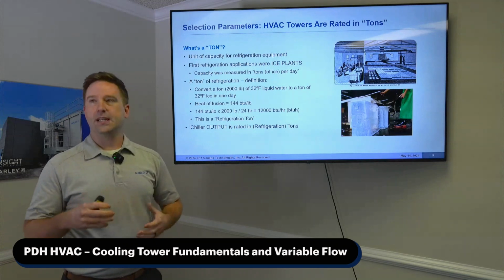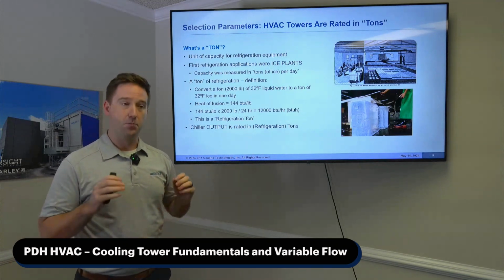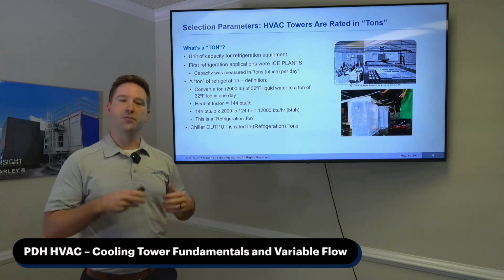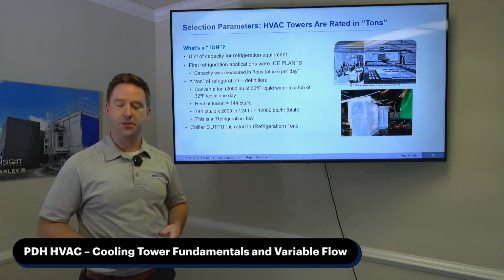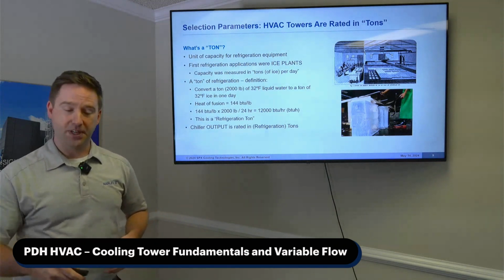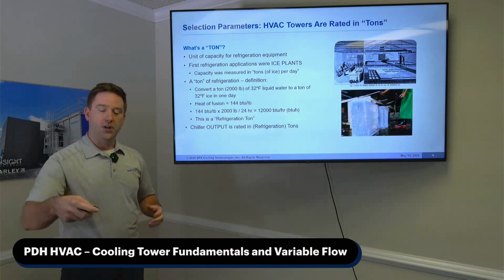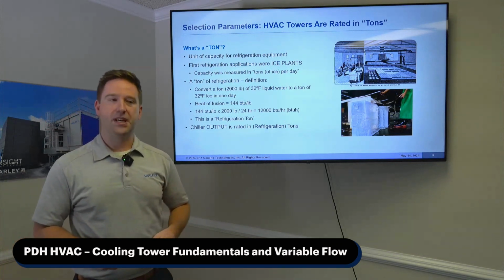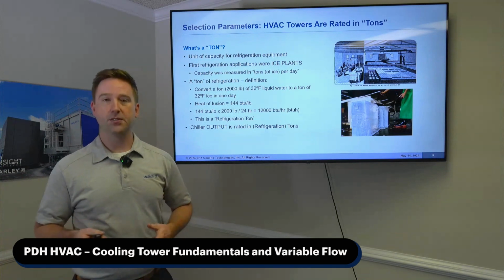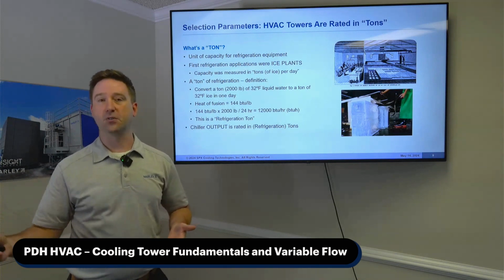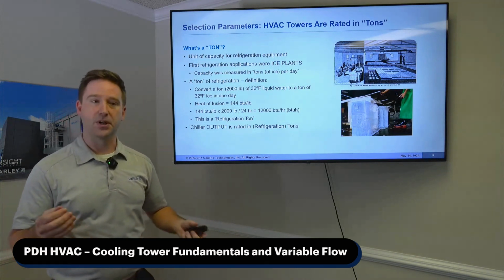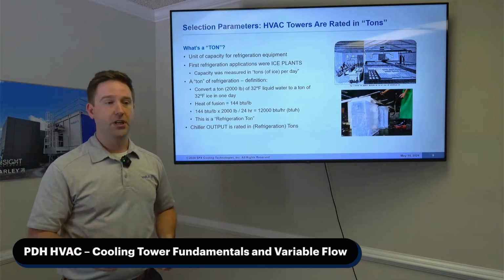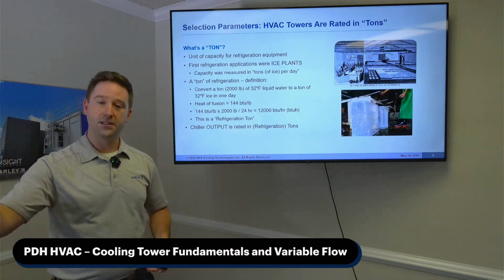So if we're going to be talking mostly about HVAC systems today, understanding what a refrigeration ton is and kind of its history can be fun and important as well. So talking about the history of the refrigeration ton, back in the day, you used to have ice plants, and those ice plants would kind of get measured in how many tons of ice they would produce in a day. So converting 2,000 pounds of 32 degree water to 2,000 pounds of ice.